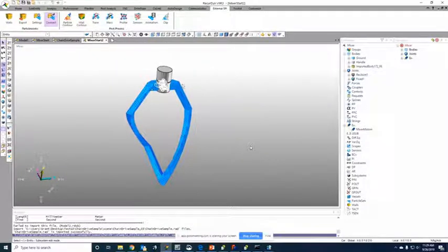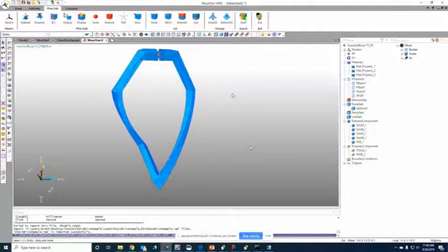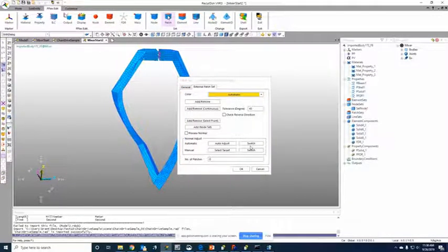The way that we'll do that is we will define the patch set right now. This is pretty much ready to go as far as the RecurDyn model is concerned. I already have the revolute joint. I already have the motion defined. I'll just double click on it to enter edit mode, and go into set and patch set. I'm going to add everything that's on this body.